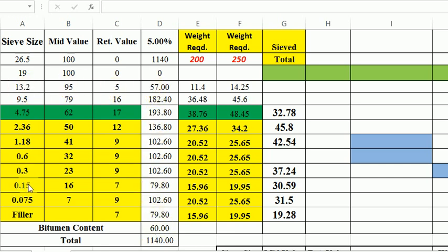Based on that, for a particular mix we can calculate the weight of aggregate based on the sieve sizes. For 6% bitumen, that value changes, it is 72 gram of bitumen. As 72 gram of bitumen is used, the aggregate is 1200 minus 72, and again, based on the retained value, we have to distribute that weight, and parallelly we have to do the mix design.